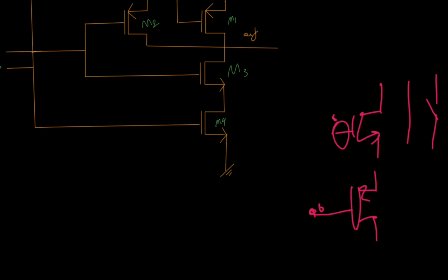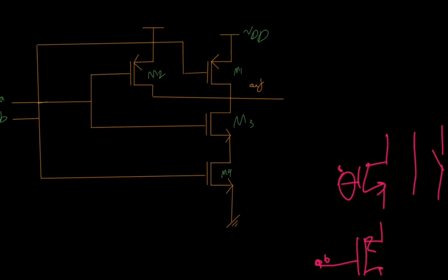That if we apply a zero on the gate, the transistor would be on and would act as a short circuit, and obviously one would make it off. So if you notice, we are giving our inputs of A and B in these wires, and the out is taken from this wire. By looking at it, it is obvious that A is being given to one PMOS and one NMOS, and so is B. B is also given to one PMOS and one NMOS, and we know that NMOS and PMOS would get turned on in the opposite of one another.